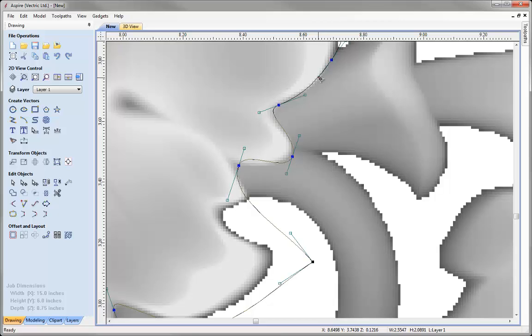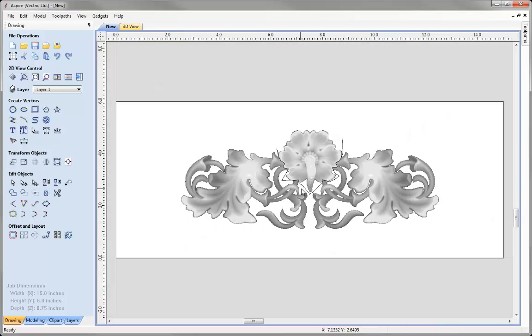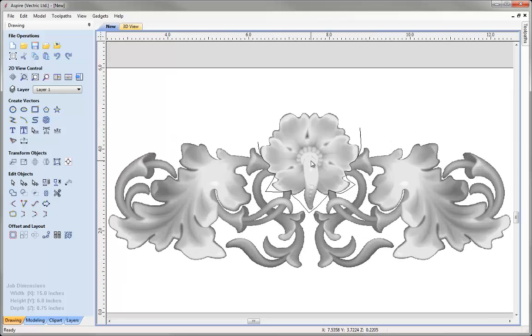Then we'll continue to adjust these. And as I say, even though this takes a bit of time, it's well worth doing because this will basically define the exact silhouette of my flower. So if these are nice clean quality vectors, then it means the edge of my flower is going to be nice and clean and have good quality too. So I'm going to insert an extra node there just to get that to bend around into there where I want that to be. So if we zoom out, now we can see where that line is.